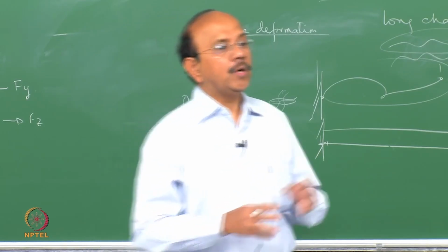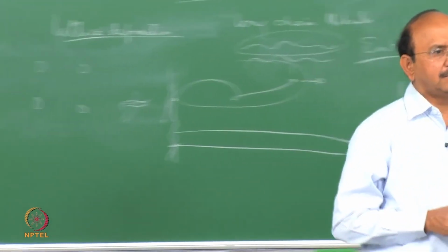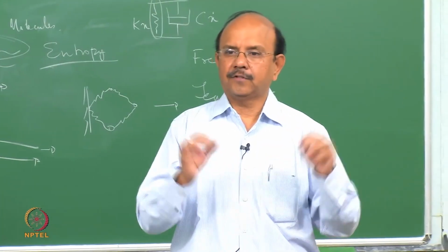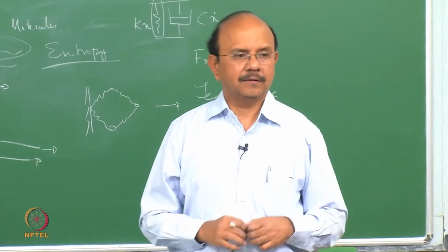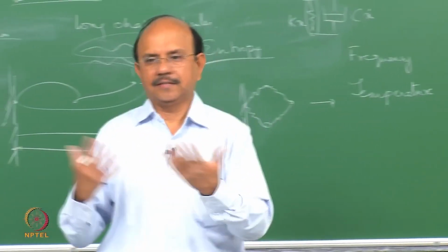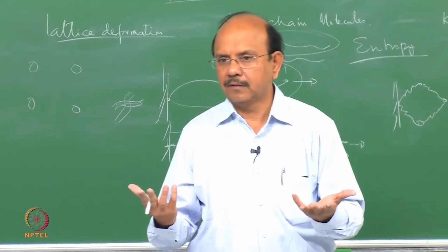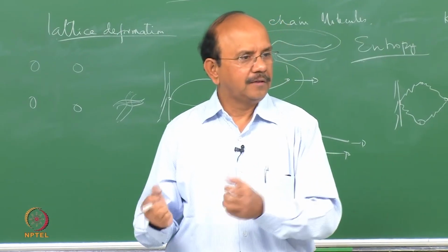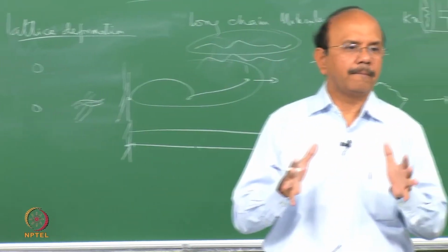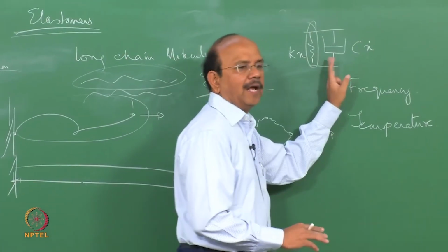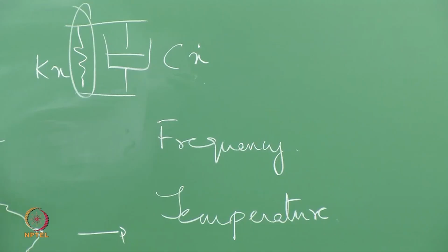So in between the two, at very low frequency, it's a nice spring because it has enough time to recover. And at very high frequency, it doesn't have time at all to recover, and hence it becomes very stiff. And in between the two, it has a spring and a dashpot effect.